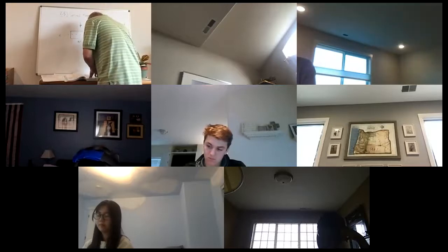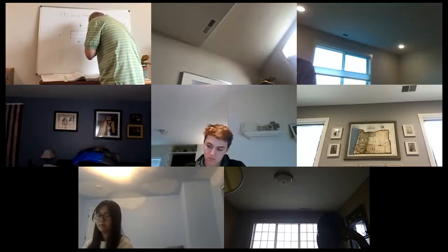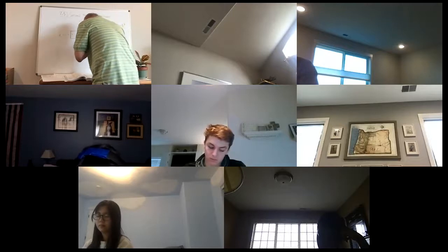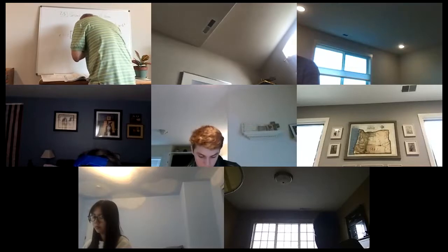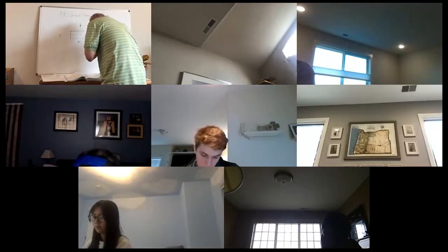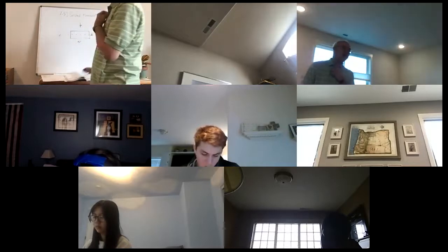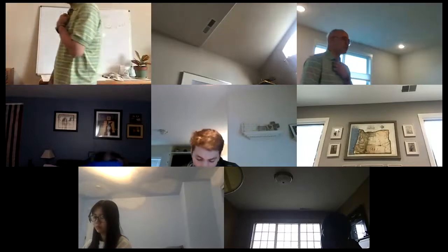If you go to table 7.8, there are examples of the second moment of area for standard beams. It gives you the beams, and it gives you the IXX and the IYY. Again, you don't even have to calculate this stuff. It's given to you in tables.